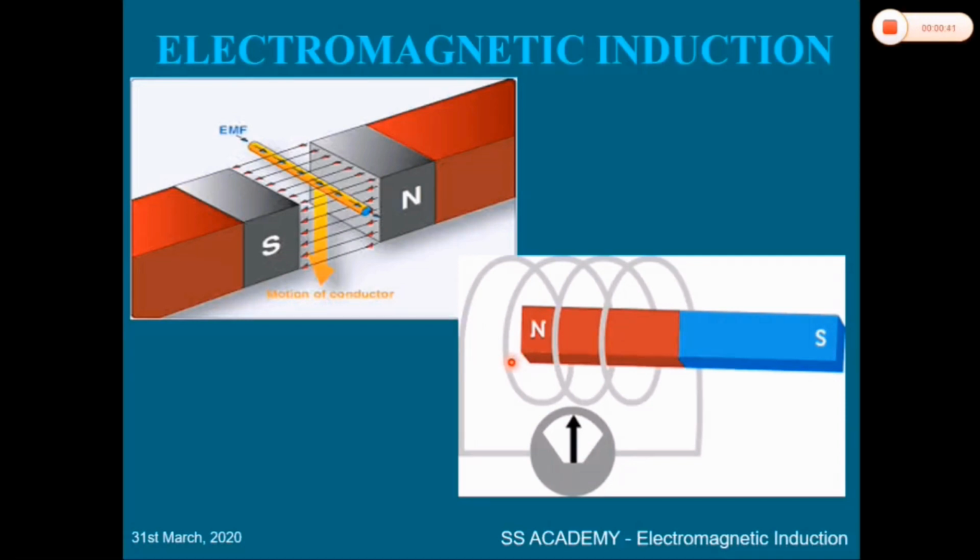Faraday's law of electromagnetic induction is the fundamental operating principle of transformers, inductors, many types of electric motors, generators, and solenoids. Generators convert mechanical energy into electrical energy using the principle of Faraday's law of electromagnetic induction. That is, when a conductor is placed in a varying magnetic field, what happens? EMF is induced, that is equal to the rate of change of flux linkage.